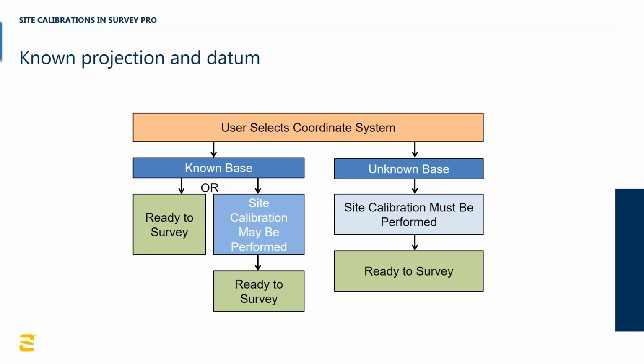Well, a couple of years ago, that NTRIP provider readjusted all their coordinates. So now they're just a centimeter or half a centimeter different here and there. In that scenario, you will probably want to do your calibration to do that little tiny, an inch or two adjustment from what the NTRIP broadcaster is now broadcasting today versus how that fit a few years ago on the control coordinates that are still being held, right?